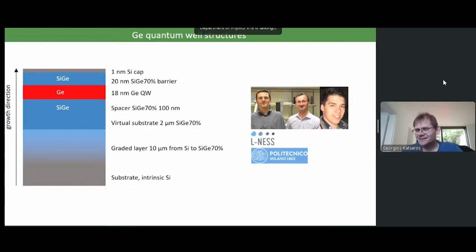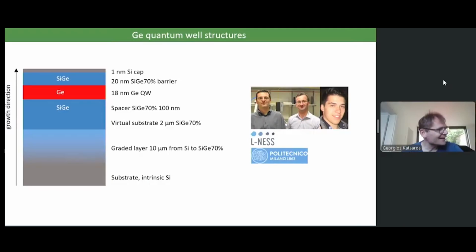Thank you. And the related question was, I saw that the quantum well width is 18 nanometer, which, very naively comparing with silicon systems, is on the wider side. Any rationale or just a choice? Okay, the honest answer is that's what we started with. We believe now that we should maybe shrink it a bit. Why so? It seems that 18 nanometers is at the limit of strain that the material can take before defects would be introduced. I get it. Yeah, that makes sense.